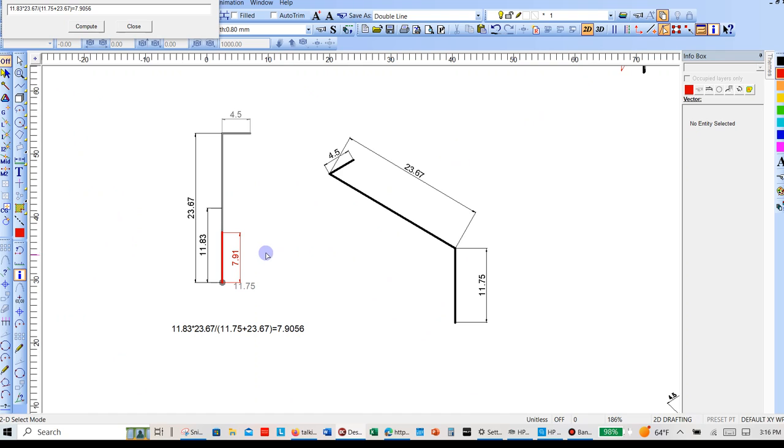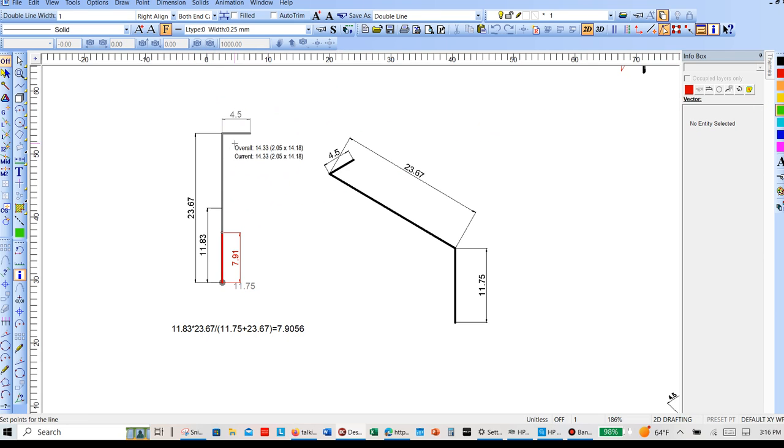All right. So now I know the center of those two, so V. I'm going to change it to the green, and then change the line type to that, and then Control K. So now I need to know along this line where the plan view of it is, right?